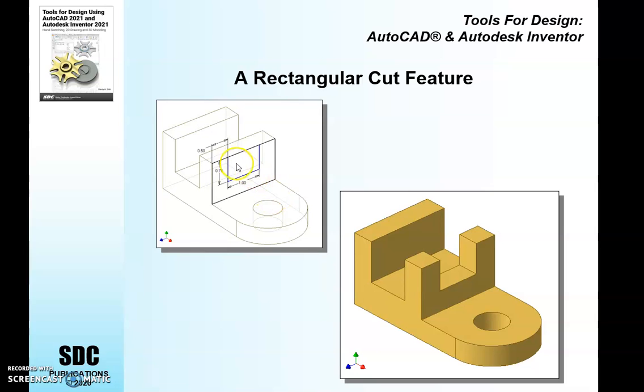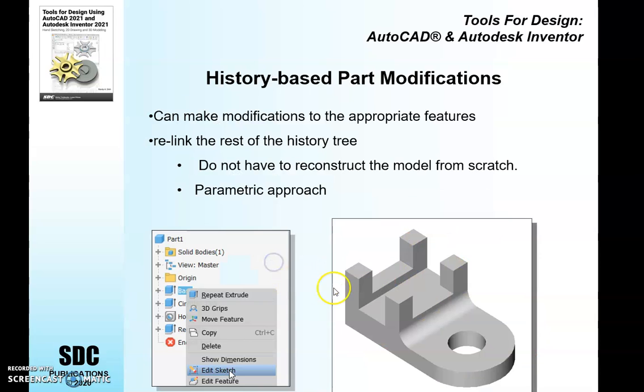And then he's going to play with the extrude, use the cut, and show you how different types of cuts work to different distances. And then we're going to show you how to go back and edit a sketch once you've got it in your browser tree, so you can make changes.